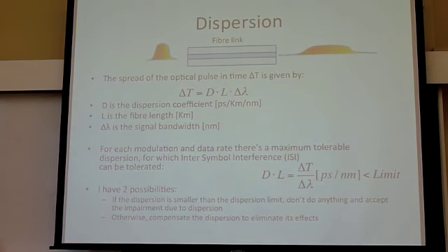So dispersion, as talked about before: this is your pulse, it goes into the fiber, and because the fiber is dispersive, different frequencies tend to go at different speeds. Since your signal is not just one sinusoid, if you do the Fourier transform, you get a bandwidth, and each part will have a different speed. What happens in time is that this is the signal you put in and this is what you get out. So it's spread out and lower in power.